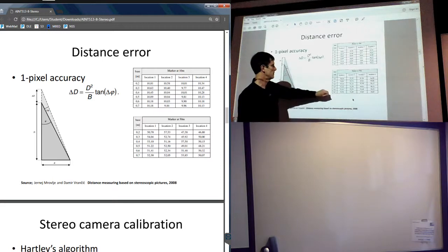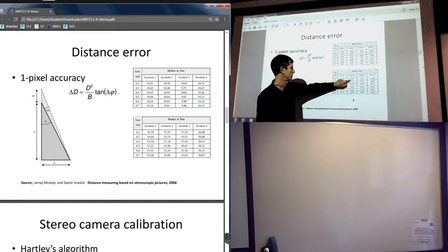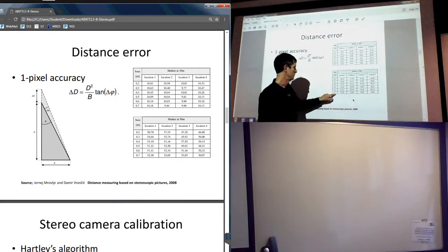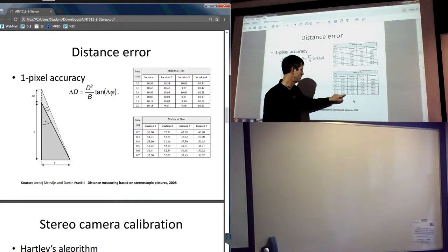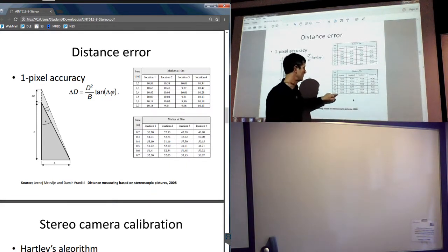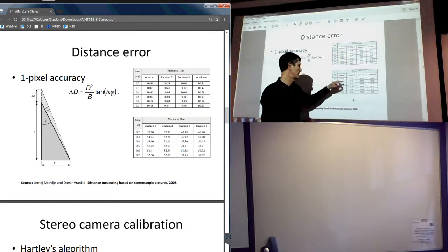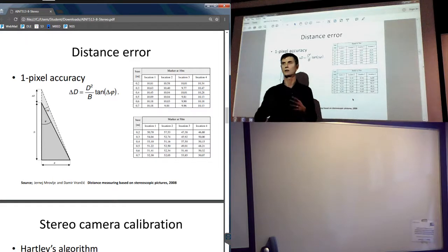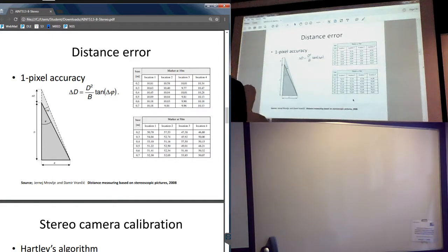Here, the marker at 50 meters gives 50.7, 57.73, 47.38, 46, and with 0.7, so with a wider baseline, you get 52.3, so there are smaller errors. And in fact, there's an error surface. You can actually find an optimal baseline for a given measurement of distance. This is something you would routinely set up if you were doing stereo photography and stereogrammetry for analysing three-dimensional scenes.